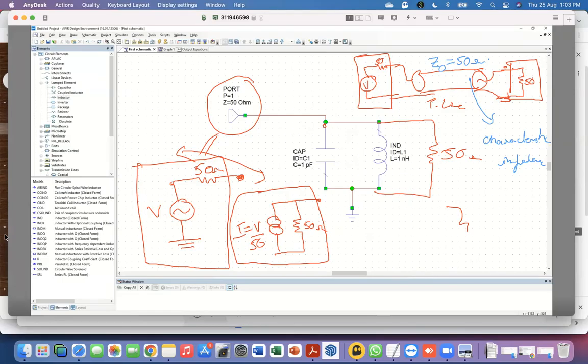Sorry, sir. Then there is the effective resistance, then 100 ohm, right, in the external circuit? So how is that impedance matching condition satisfied? That's a good question, but it's not 100 ohms. So this is why I use that word. Characteristic impedance is not the same as resistance or impedance, and we will look at that in more detail.